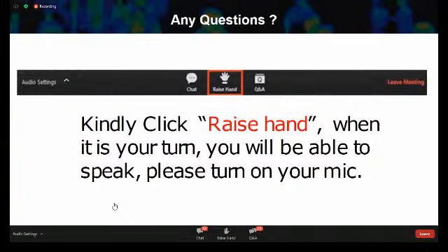Yes, this is Jamil Al-Mani from Arabian Security. My question is regarding outdoor solutions. We have many customers asking for solutions for outdoor use, for example any thermal camera or thermal terminal. Do you have anything for outdoor use? Actually, no. We don't have outdoor terminals. The reason is that outdoor temperature will affect the temperature reading. If you have an outdoor scenario which is covered and the outdoor temperature itself is less than 35 degrees, maybe we can make use of our devices. But in a totally open outdoor environment, we don't recommend this device. Thank you very much. Welcome, sir.